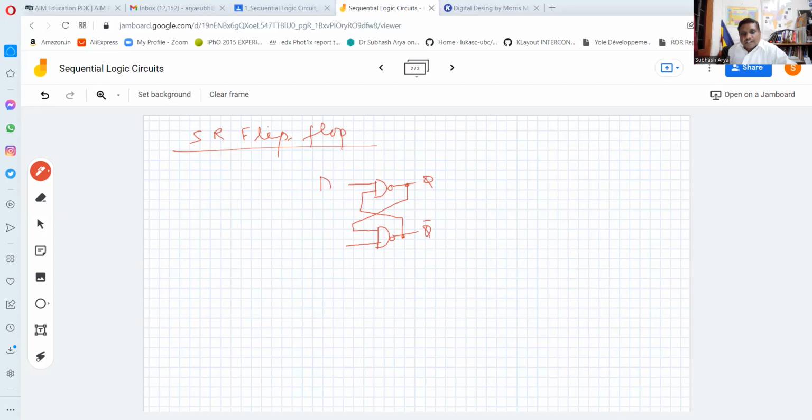But the only difference is that from SR-Latch to SR flip-flop, there is one more NAND gate where we will give here S, and here R, and the common enable circuit. Here we write enable, or we can write clock also. So first thing is clock is going on here, and this is the output. So let us try to understand this truth table, or more specifically, functional table.